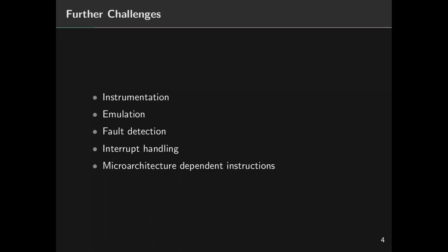So what does this mean, read-only memory? We will need to flash it to change its contents. However, on the other side, firmware might be encrypted or signed by the vendor. So instrumentation is harder than on desktop systems. Likewise, emulation is challenging. While on modern desktop systems all abstraction and hardware interaction is handled by the kernel, which can be easily abstracted by an emulator, we don't have these comprehensive possibilities for embedded devices.